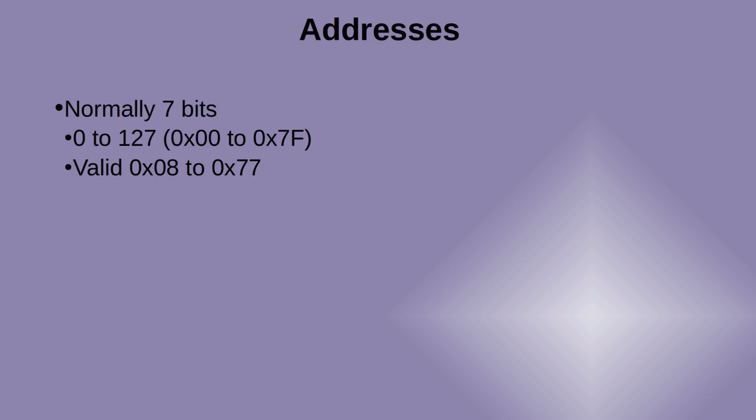Addresses can be defined in software. This is normally the best, as it means that you can potentially set any address. This is what we'll be doing on the Arduino and Pico. The only negative thing is that the way I implement it means that you'll have to recompile the code to change the address. Although it does mean that you don't have to lose any of the pins of the processor to code the address with.